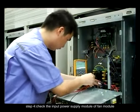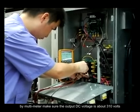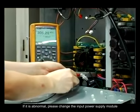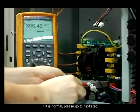Step 4. Check the input power supply module of fan module by multimeter. Make sure the output DC voltage is about 310 volts. If it is abnormal, please change the input power supply module. If it is normal, please go to the next step.